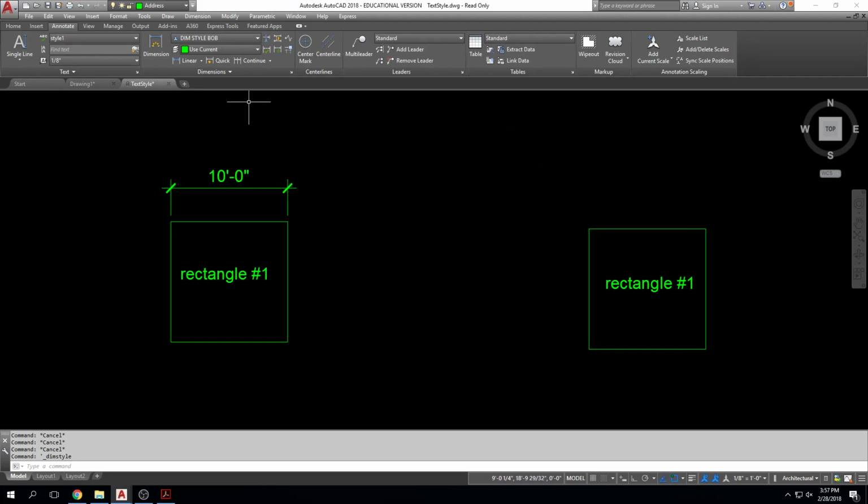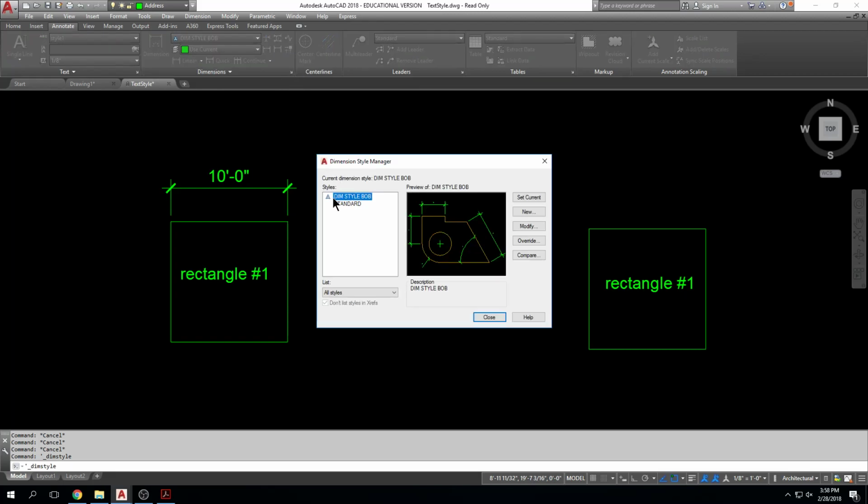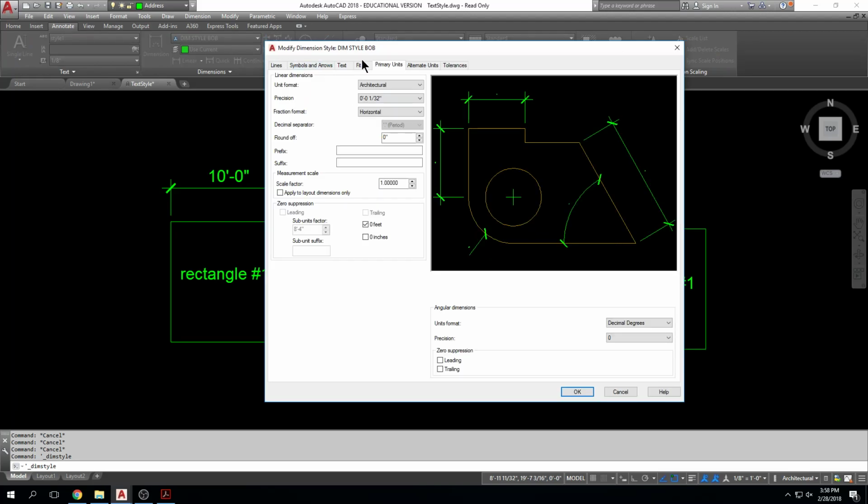Okay. So by defining all those dimension dialog boxes, I created a dimension style. And now that dimension style, when I want to create a dimension, it's there for me to use. If I want to edit that dimension style, I would just click on this little flyout, click on dimension style, modify, and I would change anything that needed to be modified.